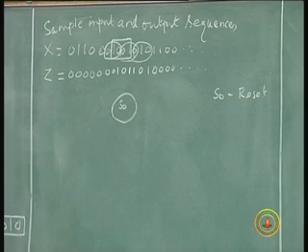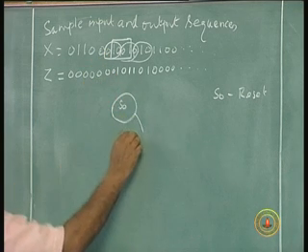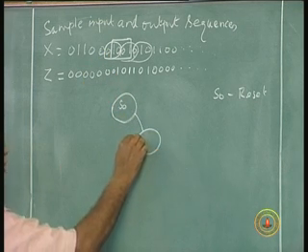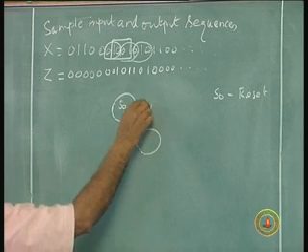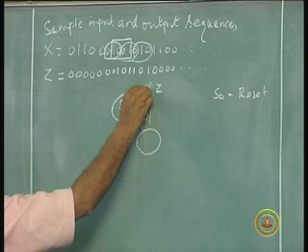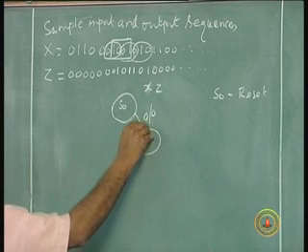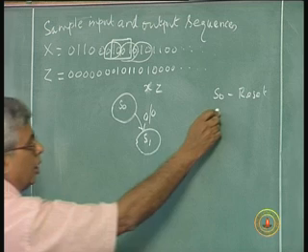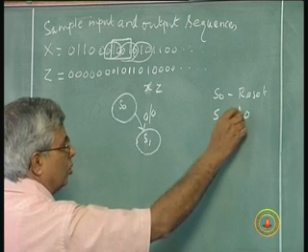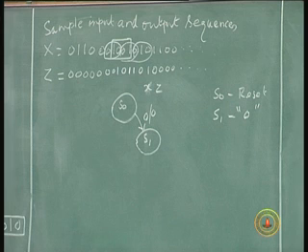The input is a 0, it could be the first bit of a pattern. If the input is 0, the output is 0. So, x and z, output is 0, go to state S1. So, S1 is a state where pattern 0 has been identified.